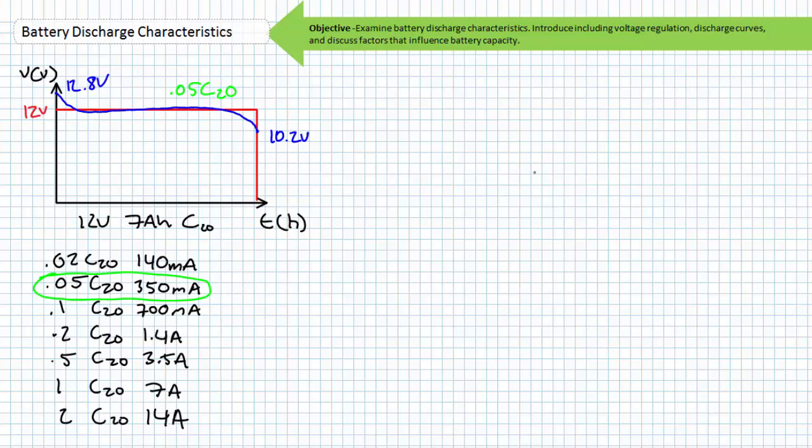In a perfect world, the voltage would start out as a flat 12 volts and stay that way. However, a fully charged nominal 12-volt battery would ordinarily start around 12.8 volts, dip down, level out for a bit, then dip down again as it reached the limits of its capacity, and the chemical reactions ground to a halt until the battery reached the predetermined cutoff voltage of 10.2 volts.